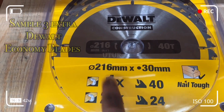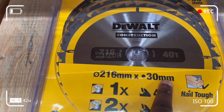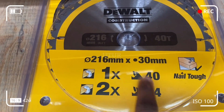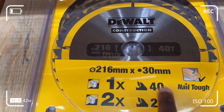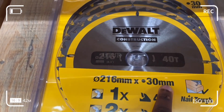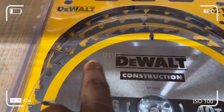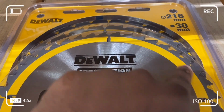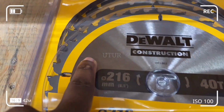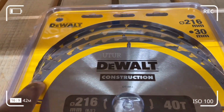We've got one 40 teeth saw blade and two 24 teeth saw blades, all of which have got a 216mm rim and a 30mm bore center. Each blade has got open expansion slots, so they're more prone to vibration, noise and blade warp. It is more probable that the 40 teeth is a combination or general purpose blade, as it's got smaller gullets, and 40 teeth falls within the tooth configuration for a combination blade.